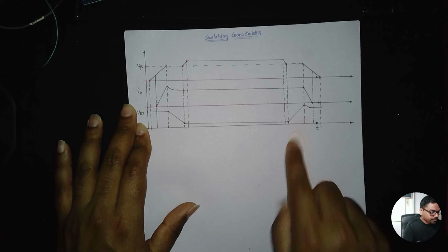We're looking at the fall time and the rise time, and how you can look at a data sheet and understand what parameters there are, and how you can draw your own graph based on the characteristics and parameters provided to you by the MOSFET manufacturer in the data sheet. Based on that information, this graph will make a lot more sense, because once we start explaining the graph and what each of those parameters means, you can look at a data sheet and understand what that really means.